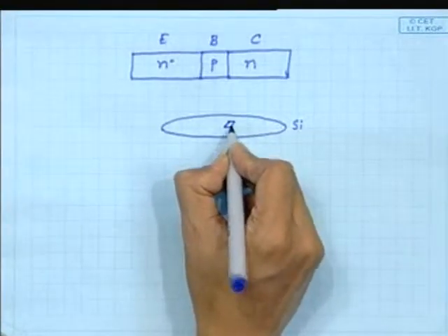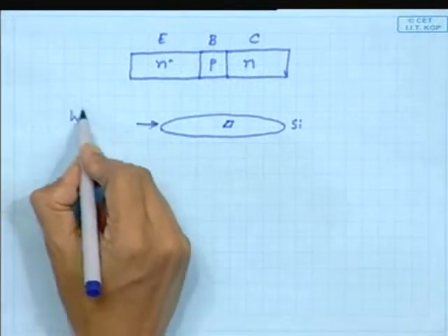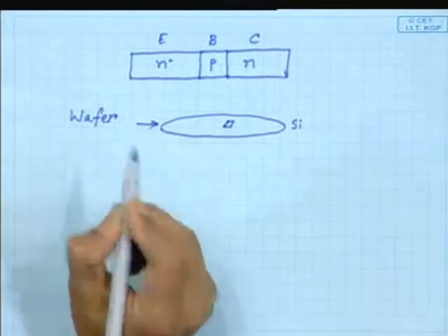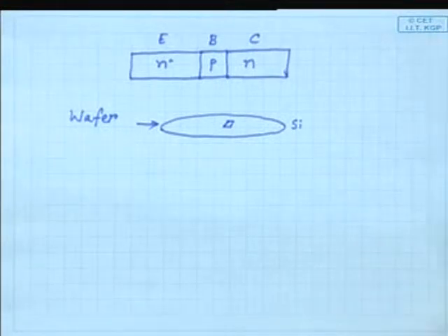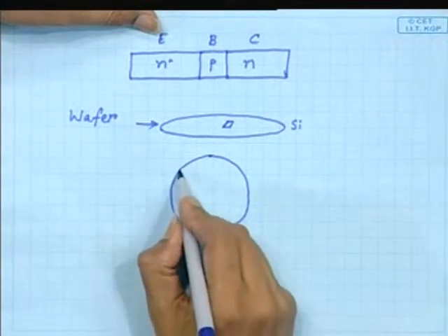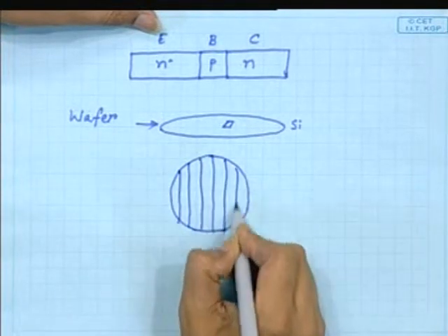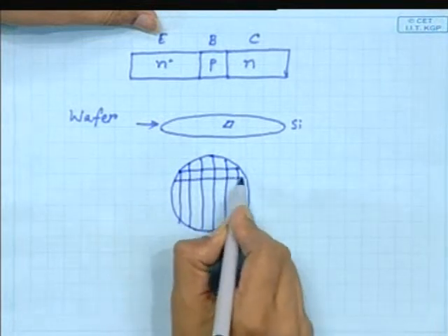Now, if you think about a small chip, it will be just a small part of that. So, in one so-called silicon wafer, this is called a wafer, you may fabricate more than 100 such microchips in a single go, and typically you use the same chip and repeat it over the whole wafer. If you take the top view, you may find several chips lined up like this. But now, how do you actually fabricate this?